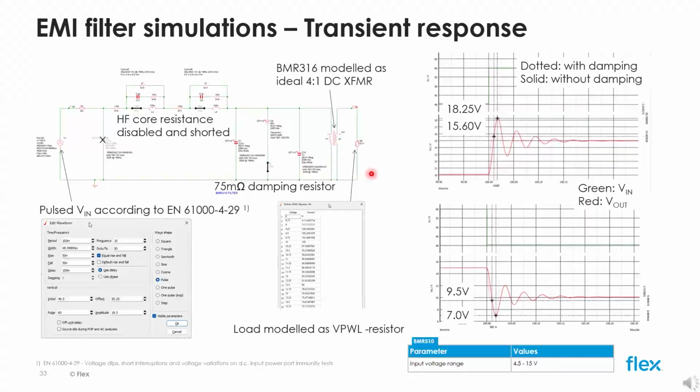A transient response simulation can be used to investigate the system response. This is a simulation technique I've learned on Christophe Basso's website, highly recommended. Here, I want to see the effect of the filter output impedance when connected to the negative input impedance of a converter. I don't want to use a converter switching model with a pulse load applied to its output because I want to keep the simulation to the bare minimum.